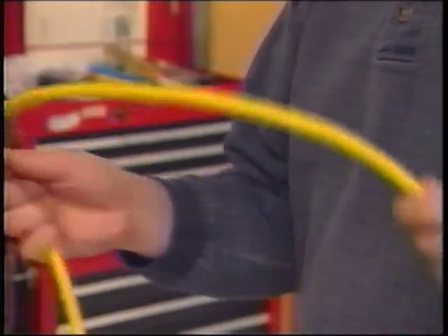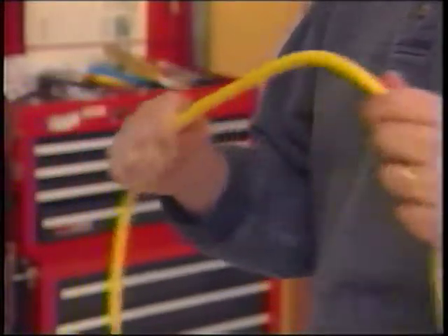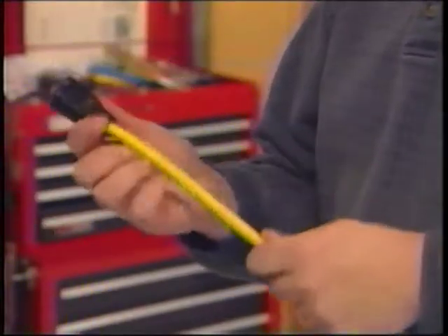When you use extension cords, keep in mind that they really are designed for temporary use only. Only cords that are designed for hard or extra hard service should be used at construction job sites. You'll see these designations marked right on the cord itself.